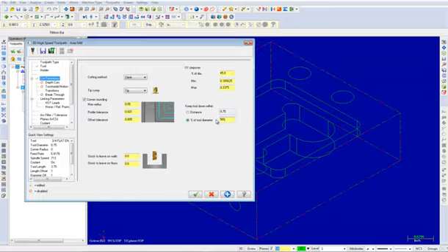I will now take a brief moment to explain a few of these parameters. Corner rounding replaces sharp corners with arcs for faster and smoother transitions in tool direction. Max radius inputs the radius of the largest arc that you will allow Mastercam to insert to replace a corner. Larger arcs will result in a smoother toolpath, but with a greater deviation from the part corner.